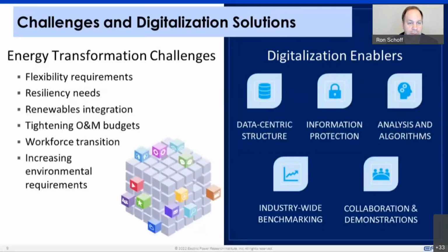So as I go to this next slide, we see some key challenges that have played out throughout the energy transformation, including the increased need for flexibility. Now that happens to manifest very early on in thermal assets that are trying to balance out perhaps some variability of the renewable assets, but we also see the need in mature systems with higher levels of penetration of renewables, that those assets need to be flexible as well. That's always been true of hydro, but wind and solar are increasingly being relied upon to provide not just grid services, but a flexible output, which drives us towards all kinds of different design and operational choices, including the integration of energy storage, more controls over the inverter, and other data-related controls options as well.